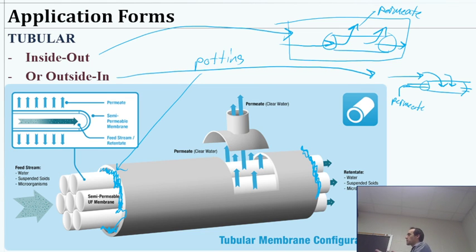And if we change that, we want to make sure that we change the membrane itself so that our separation layer is on the outside if we're doing outside in, so that we're not getting all the junk particles collecting on the inside of all the space in the membrane that's not actually doing the separation.